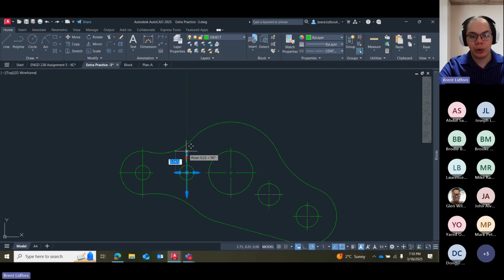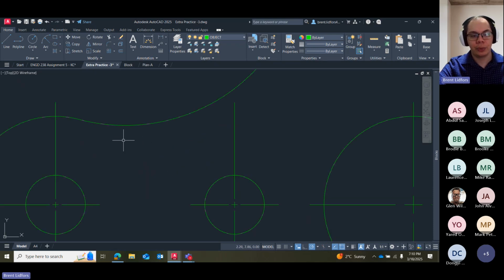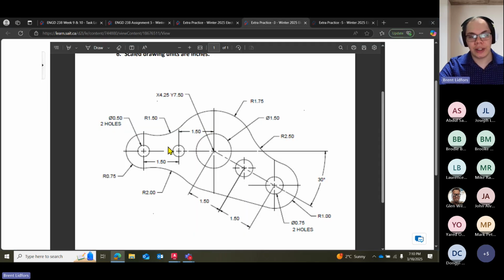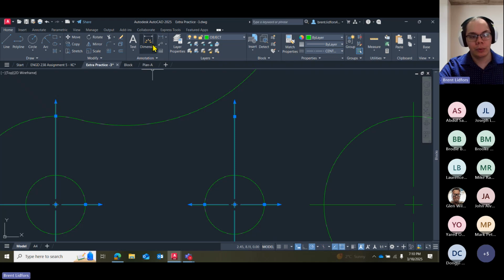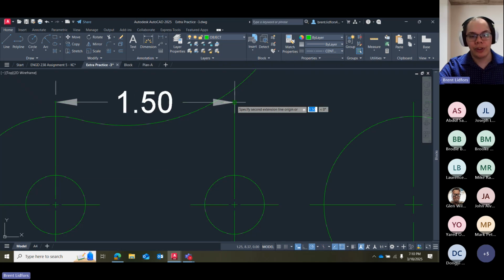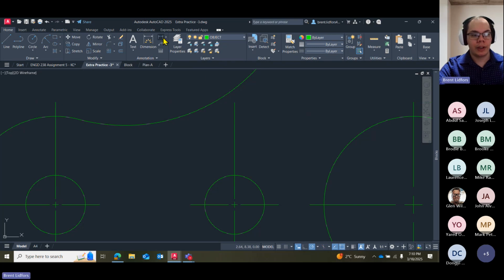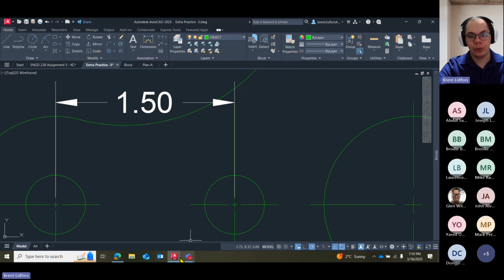These also make good extension or grip points for dimensions. So you can see that these ones have been matched in height, just like in this drawing here, such that they can put a dimension in here and match them up as well. So they could take a dimension. They could use the ends if they wanted. Or they could use the full center point. But it gives you a few extra grips if you choose.